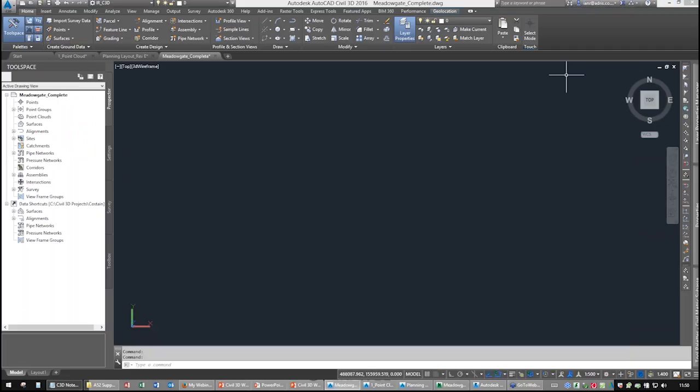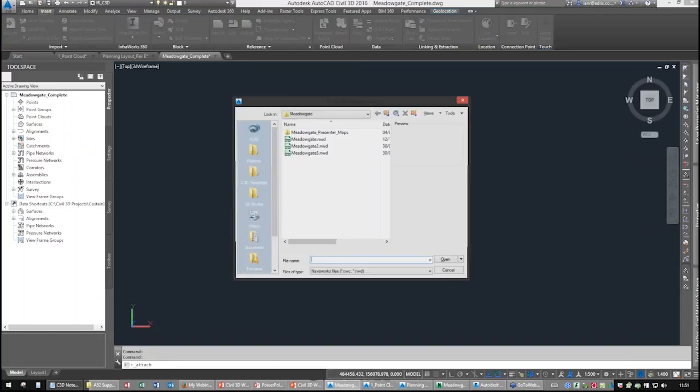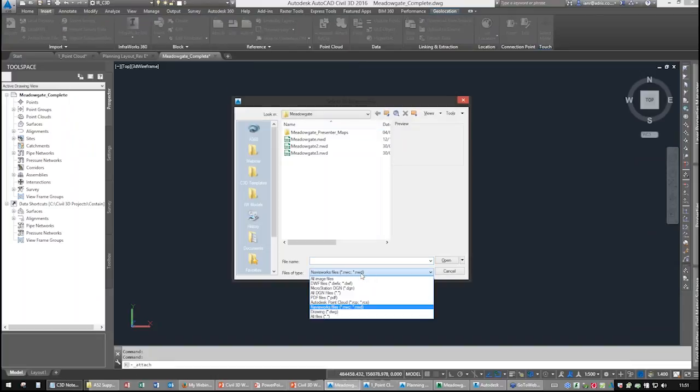And that's what's changed this year, because in the Insert tab, I can go in and I can just simply attach, like you would a normal reference file, and there you go, you've got the Navisworks files have been added in there. So yes, I could have attached DWGs, DWFs or whatever, but I can also now attach Navisworks.